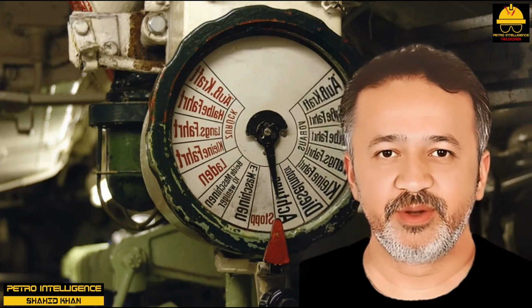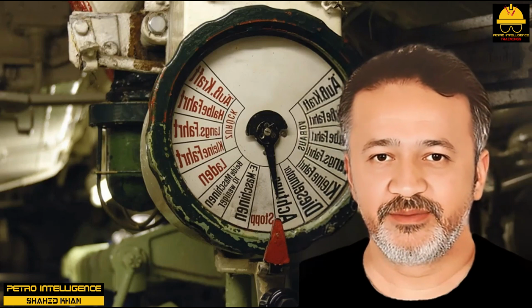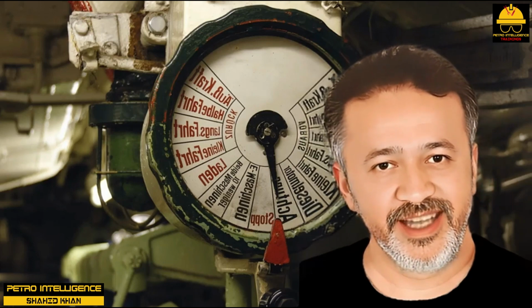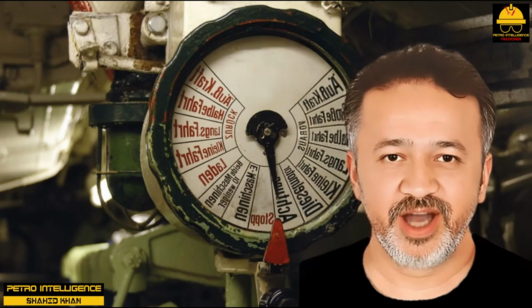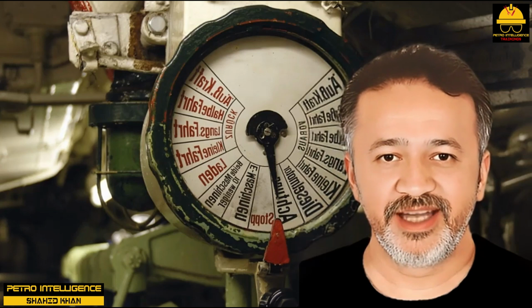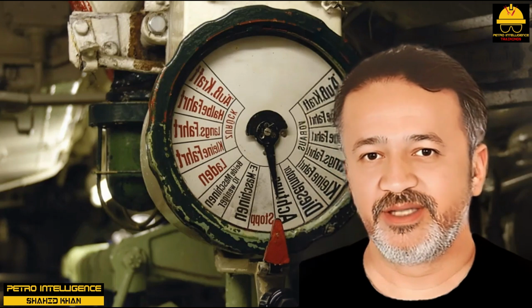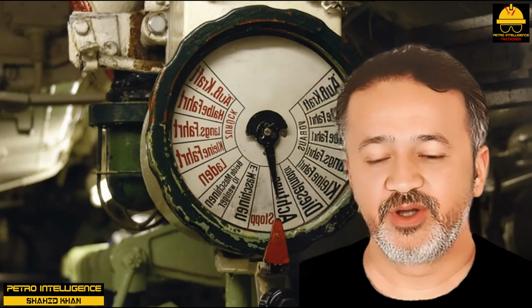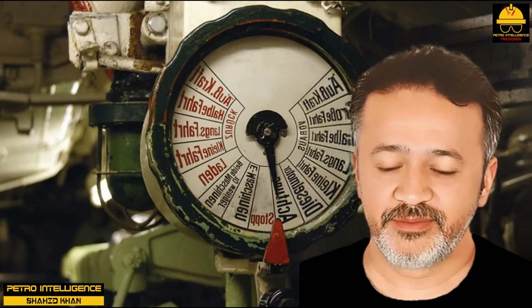A control loop is a group of instruments that work together to control a process. These instruments typically include a transmitter coupled with a sensing device or primary element, a controller, a transducer, and a control valve. The controller receives a signal from a transmitter, compares this signal with a set point, and adjusts the final control element, process to stay within the range of the set point.